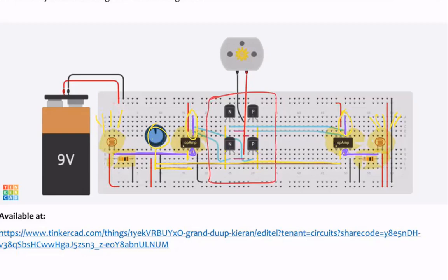And I'm going to show you what exactly they do, okay? These are usually transistors that we learned yesterday. The N that you see over here means it's an NPN transistor. P would mean this is a PNP transistor. You know the difference between the PNP and NPN now. In NPN, electrons take part in the conduction. In the PNP, it's the holes that take part in the conduction. Electrons have higher mobility, holes have slightly less mobility.